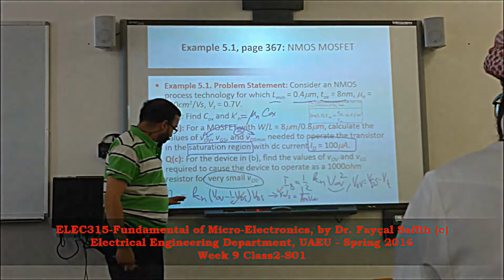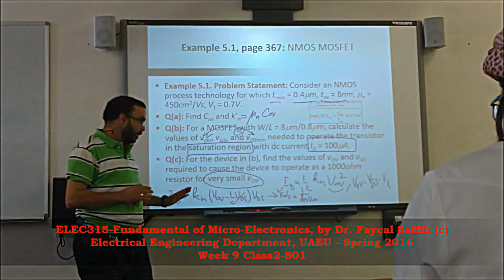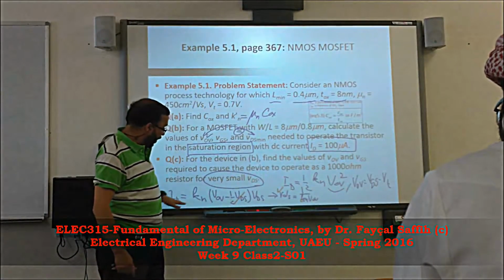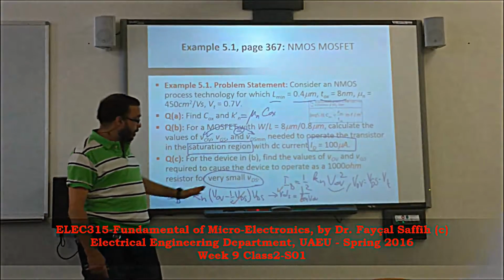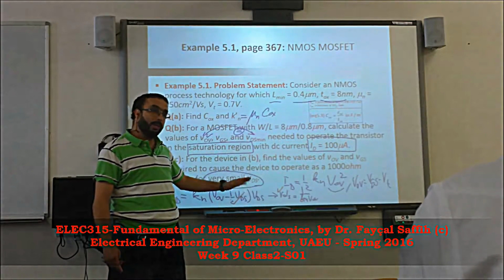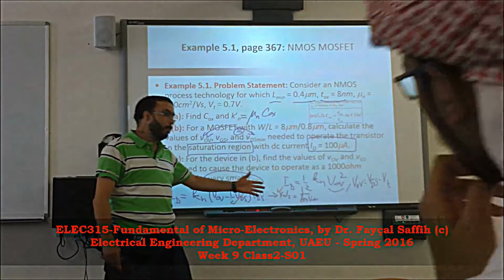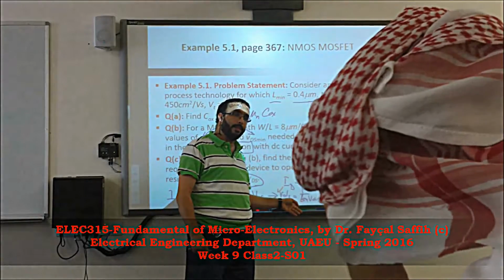It's very easy actually. We said that the MOSFET, in low VDS, has a linear relationship between ID and VDS. In Ohm's law, if I write ID versus VDS, the constant between them is 1 over R. So you take this, flip it, and that's my resistor. Got it?